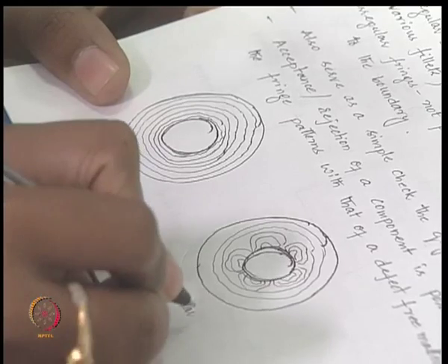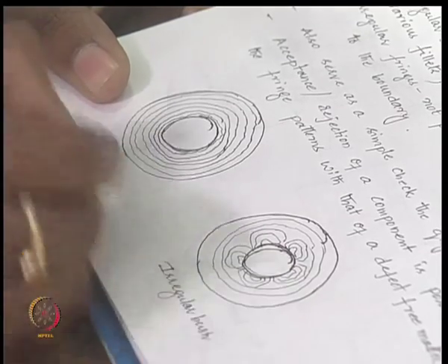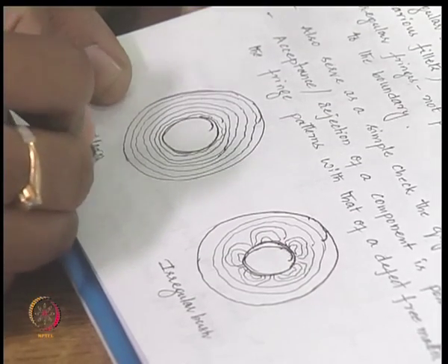So, simple experiments are really very difficult to conduct, even a simple tension. One of the ideas they suggest is if you need to verify the alignment, go for optical techniques and improve your alignment based on that.